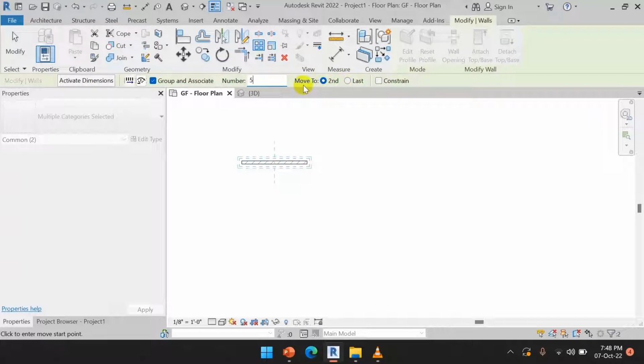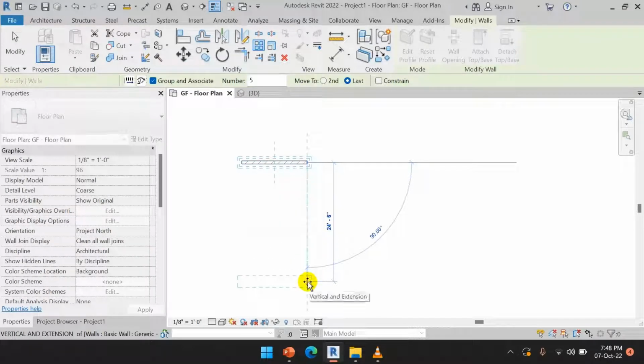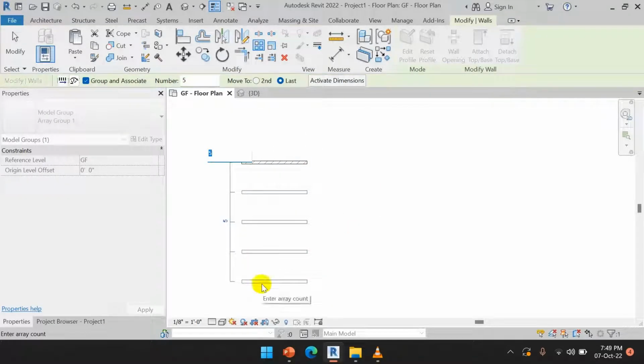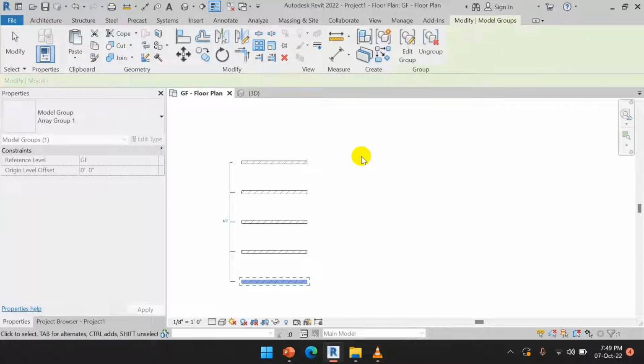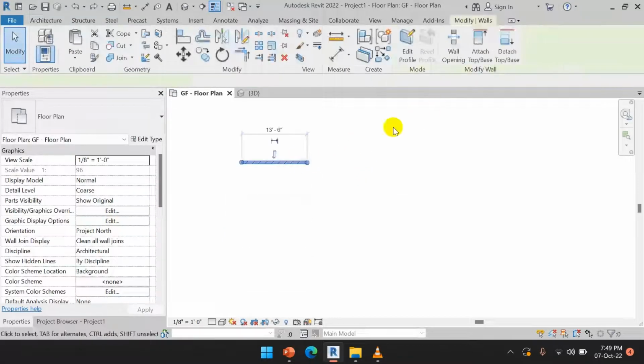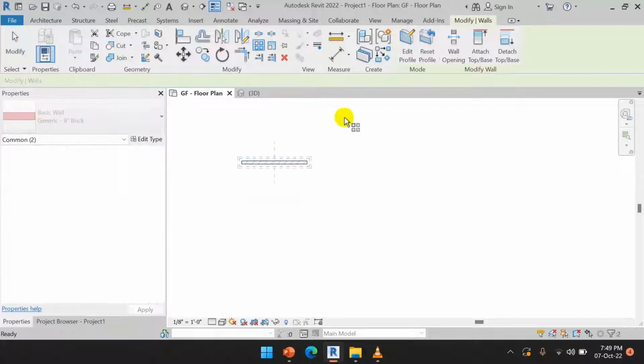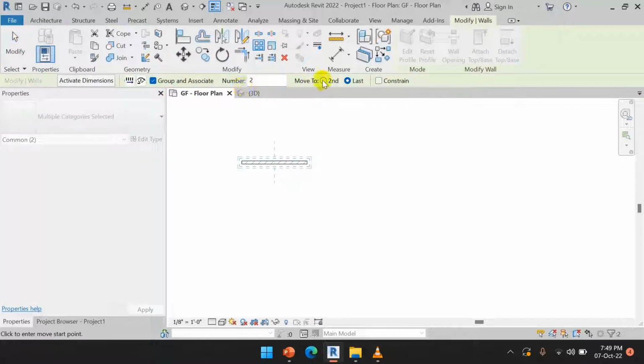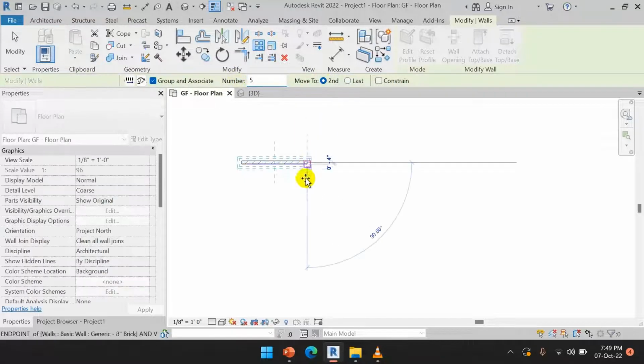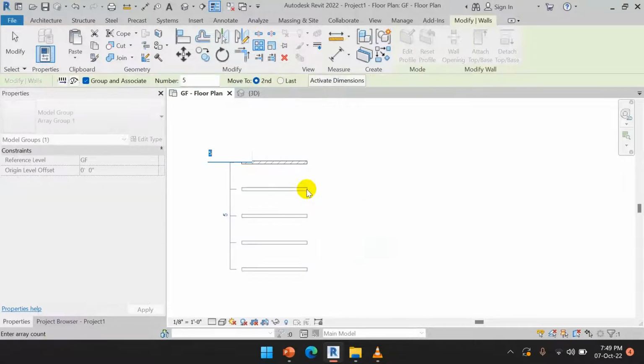First to second or first to last? If you specify first to last, with five numbers, the distance provided is from the first point to the last point. With first to second, you are specifying the distance between the first point and the second point.